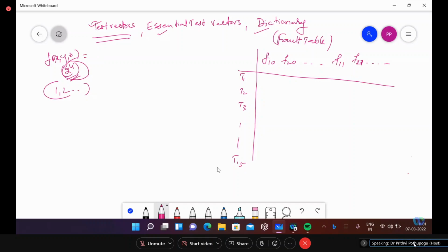In this, our design should have a minimal number of test vectors so that our design is perfectly working. If we have to say that our design is properly designed, the number of errors happening in the design should be minimal. Okay. So this experimentation will give us information regarding on which line what type of fault is happening. The second subscript says what is the type of fault, and the first says what is the line. Okay. And corresponding to which test, what is the type of fault happening.